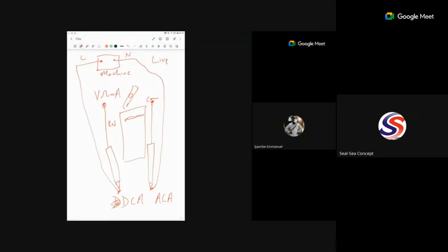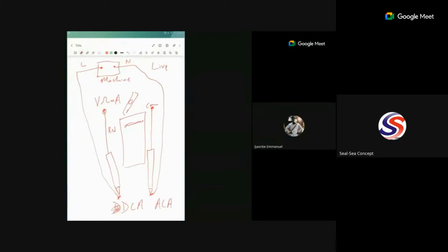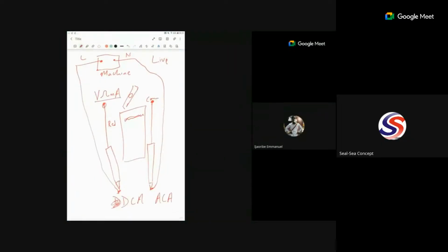Your probe for the current also will still be on this. As you can see here, it can measure voltage, ohms, which is resistance, or your ampere, which is current. So milliampere. So it can actually measure it. Your red probe will still be there, and your black probe will still go to com, and then you measure again. Again, you can test for current on a live circuit.